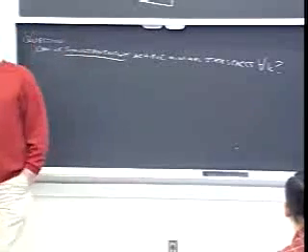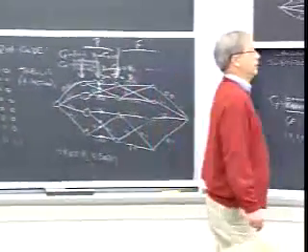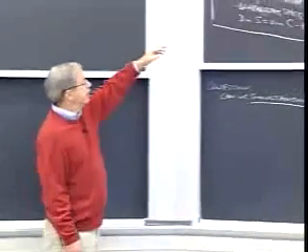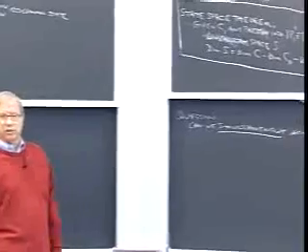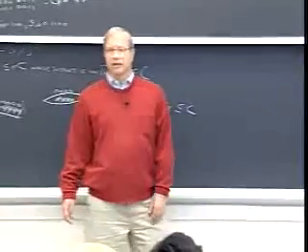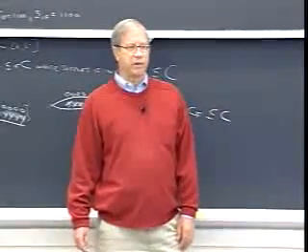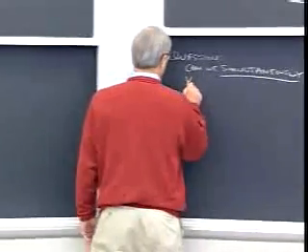In other words, can we draw a single trellis which gets the minimal state space at each time? We haven't proved that there is. It might be that if you push in the state space at one time, it forces the state space to balloon out at another time. And in fact, for nonlinear codes, that is typically what happens. But for linear codes, a minor miracle occurs, and the answer is yes.